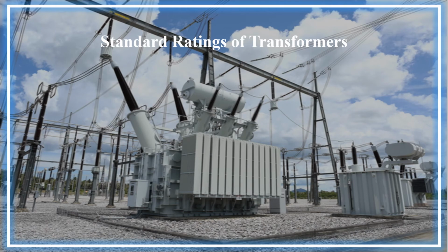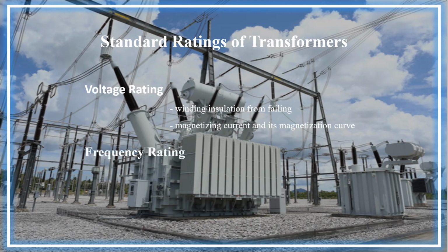Standard ratings of transformers. Voltage rating. It is important to know the voltage rating so as to protect the winding insulation from failing because of an excessive voltage applied. At the same time, to have an idea about the magnetizing current and its magnetization curve of a current transformer. Frequency rating. The most commonly used frequency ratings are 60 Hz and 50 Hz. In our country, Philippines, the standard frequency is 60 Hz for electricity grid.